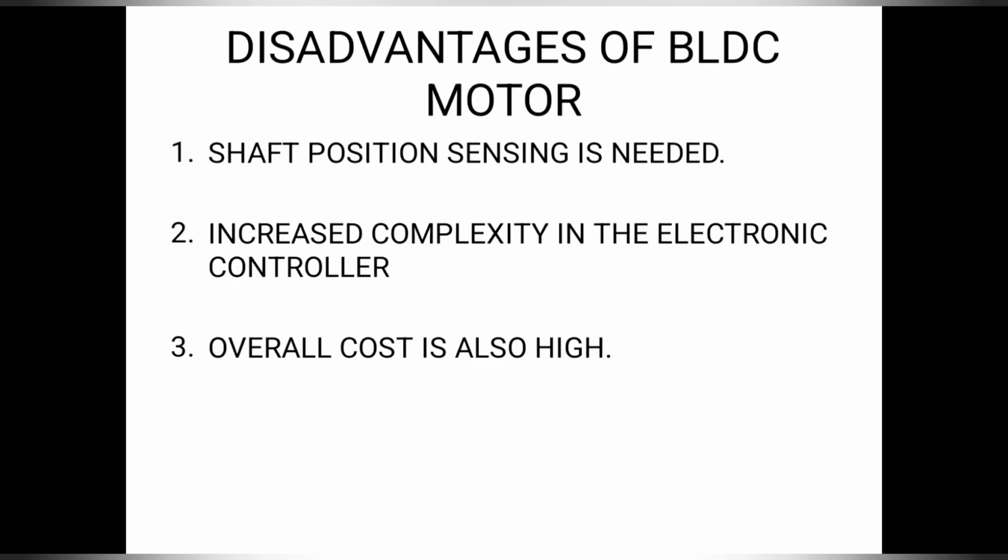Though we have several advantages with the BLDC motor, we have a few disadvantages. The shaft position sensing is needed. We need a separate unit for position sensing. Increased complexity in the electronic controller, so it is again a design aspect. And overall cost is also high. So these points should be kept in mind as disadvantages of BLDC motor.